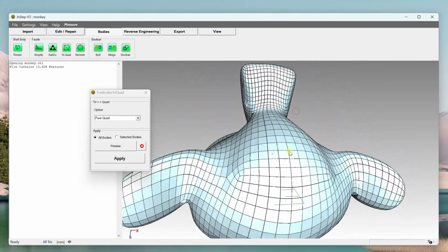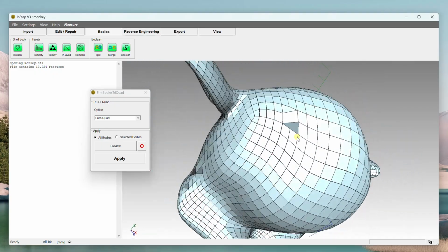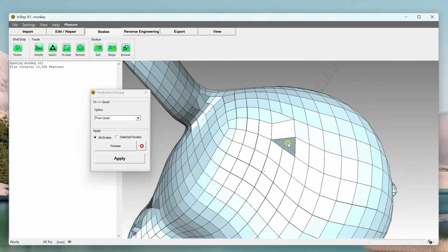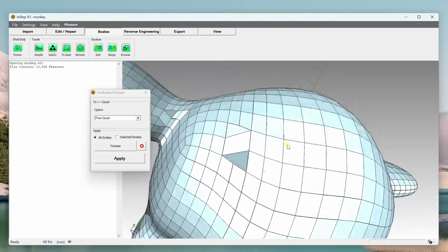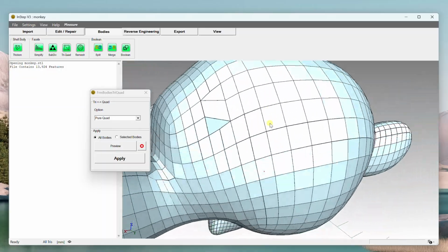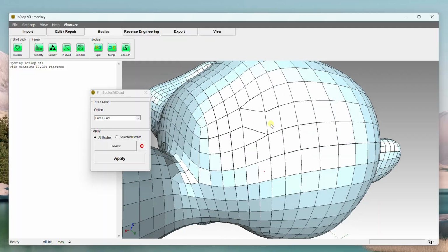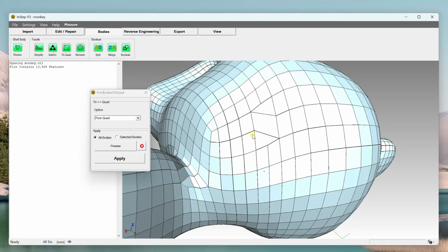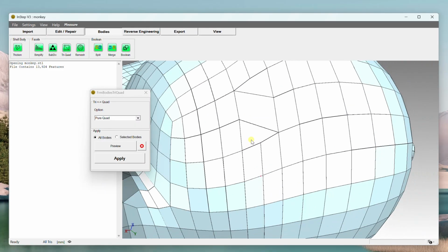What you'll often see with these meshes is that you'll end up in places where the surface doesn't look quite correct, and that's got more to do with the fact that a triangle is guaranteed to be on a plane, whereas a quadrilateral is actually not.